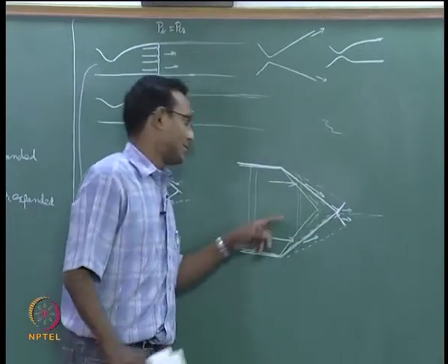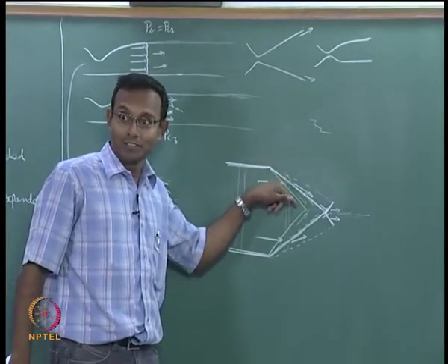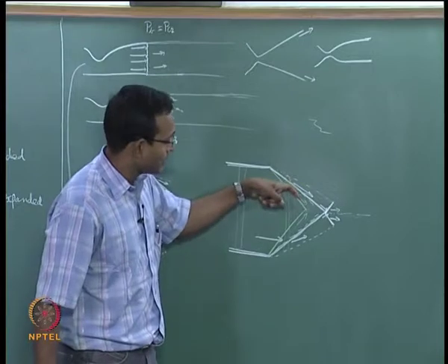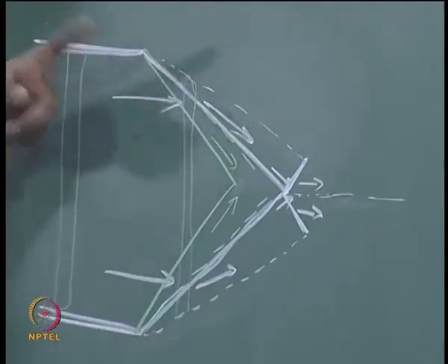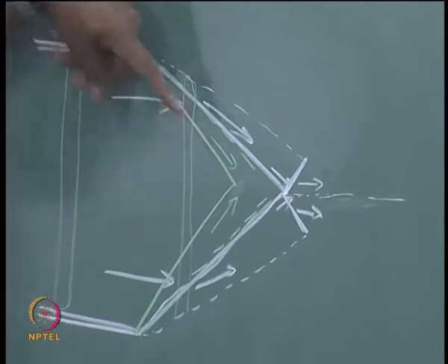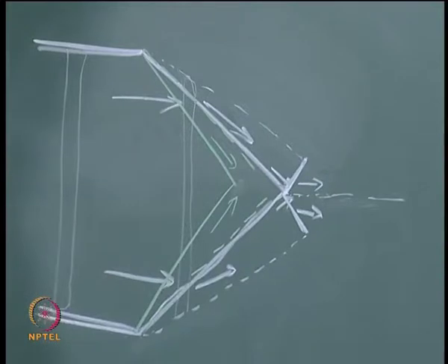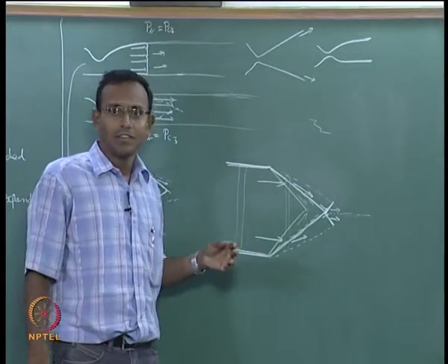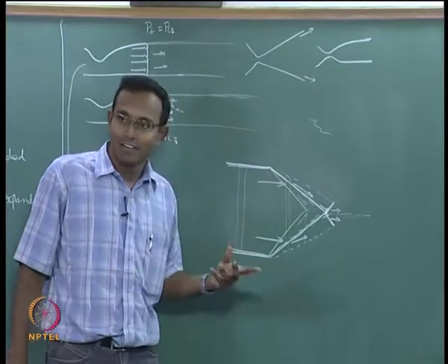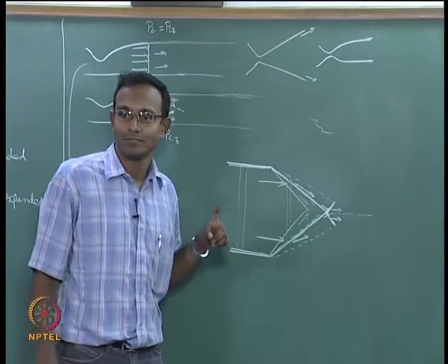But remember, stronger oblique shocks will have much lower Mach numbers downstream of it. So, the Mach number downstream is lower compared to the previous downstream Mach number, and the angle that it has to turn by is now higher, right? A weaker Mach number flow has to turn high amounts. Sometimes there will be a point where it will not be possible for it to turn by an attached shock.